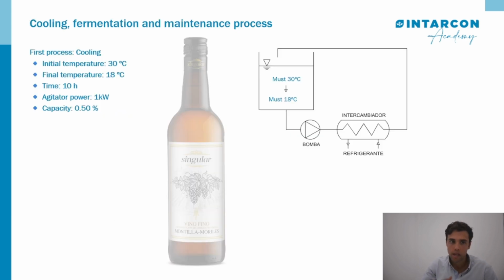At first, the first process will be cooling. We have an initial temperature of 30 degrees up to a final temperature of 80 degrees in a time of 10 hours. We will also have agitator power, and as we said before, a capacity of 50% of the tank.